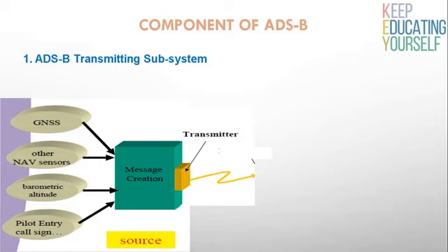and will be configured so that selection of the ident button will activate both SSR and ADS-B. Occasionally, an ADS-B equipped aircraft with a system linked to the transponder control box will not have a separate on-off switch, and the ADS-B function will be on whenever the transponder is on. If ADS-B is installed as a freestanding unit, then it will have its own control box with ident button and on-off switch. This last option is not yet very common.